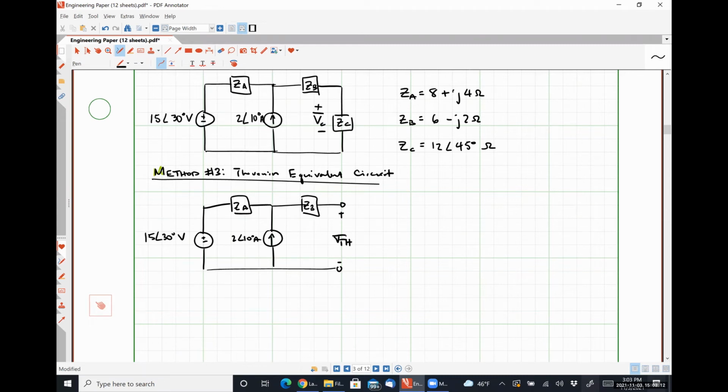So, okay, so let's write that down. This voltage VB must be 0. Everybody understand why? Exactly right. There's no current flowing through the impedance, so there can be no voltage drop over it. So that leads us to an interesting revelation here. All of the current being supplied by that 2 angle 10 amp source, which I'll draw in blue, has to flow through that impedance ZA.